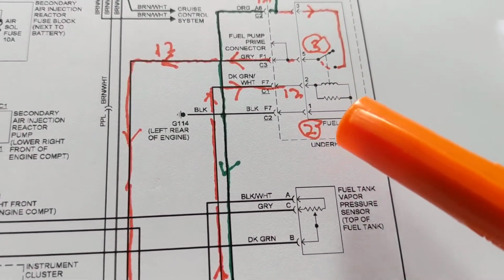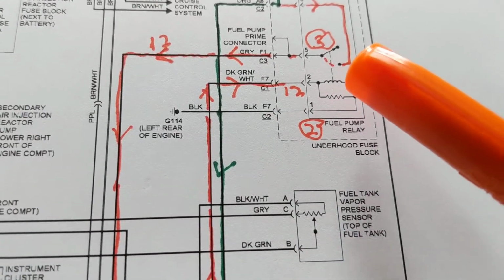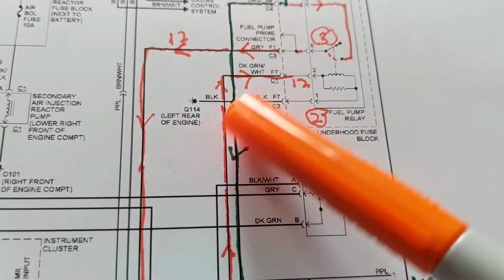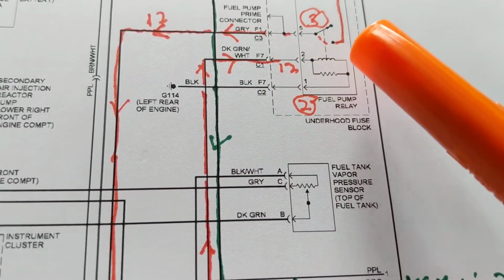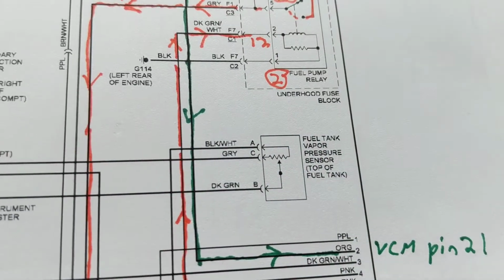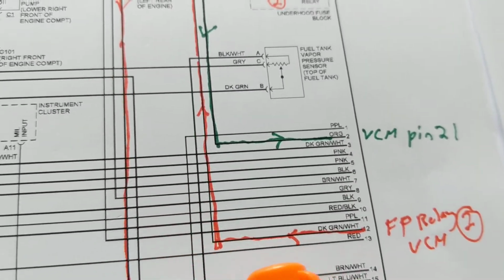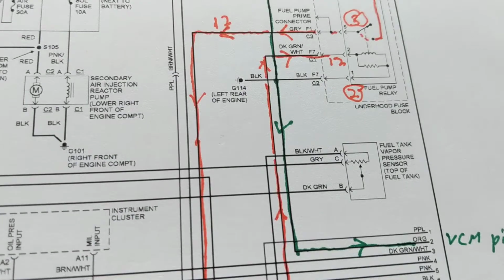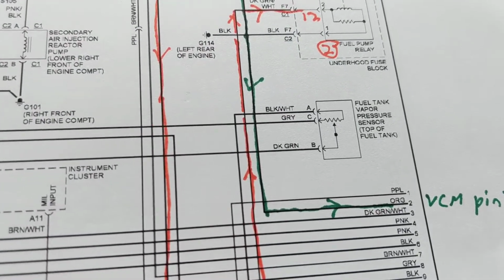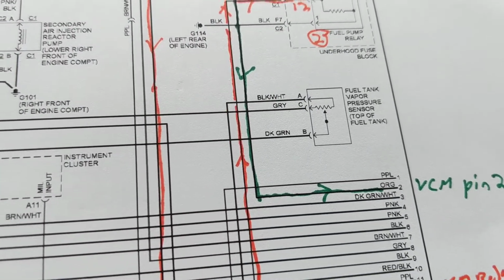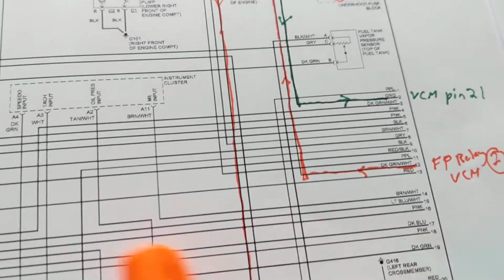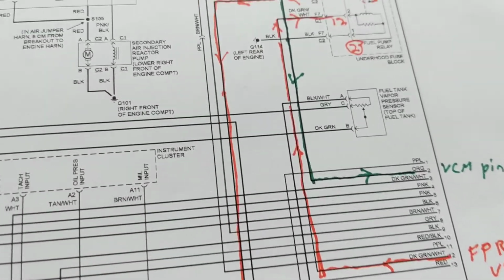You have to know how it works. You have to know which is the load side, which is the control side, which is being turned on. You have to know, is the input to the relay, or is the relay an output? Especially with computers, you have to understand which one is the input and which is the output. Fuel injectors, the grounds are controlled by the computer. You have to know, is it an output, is it a computer? So it's more than just highlighted traces.